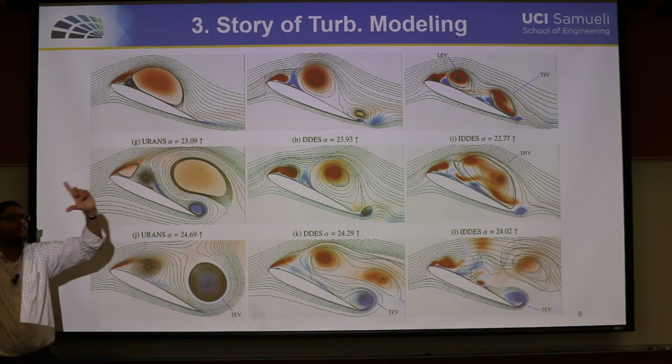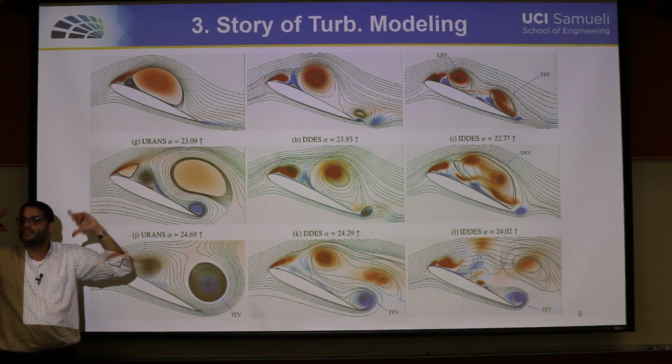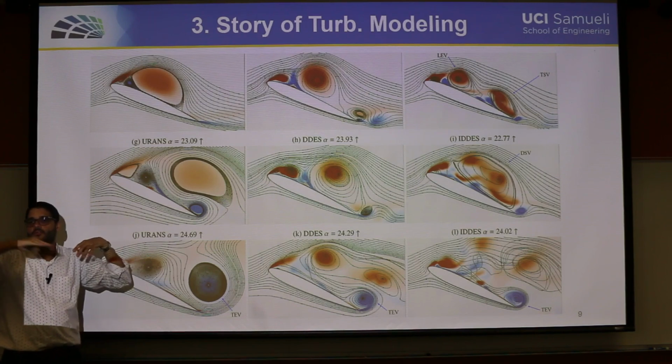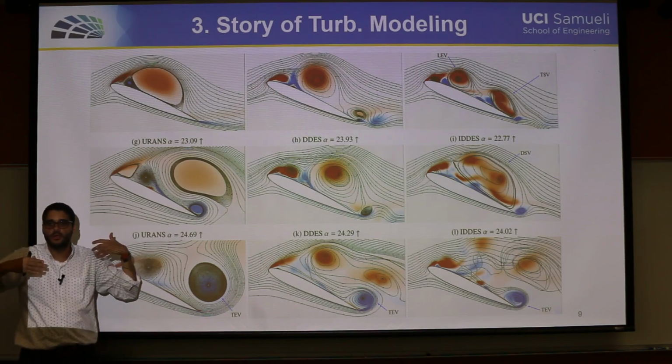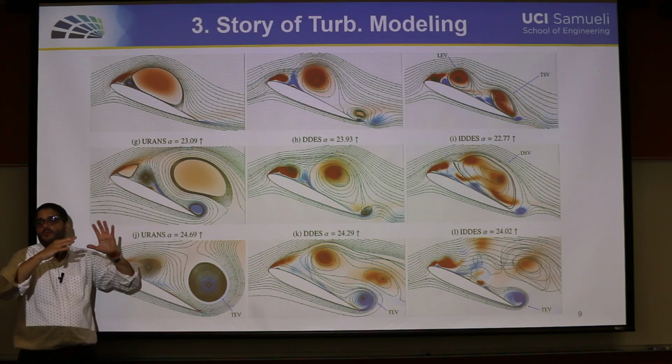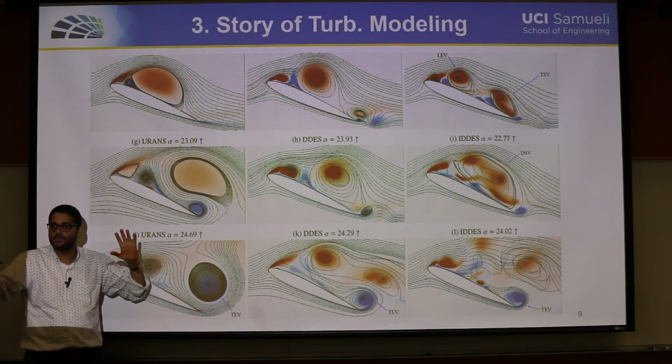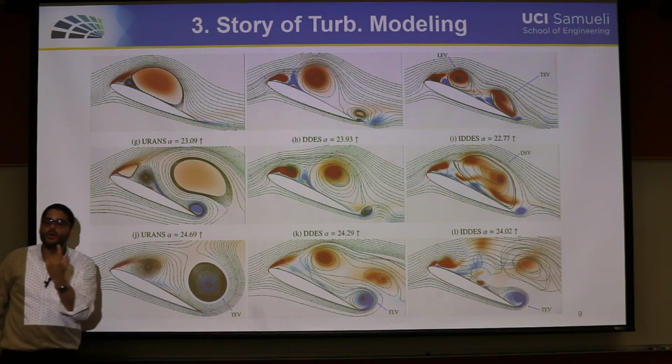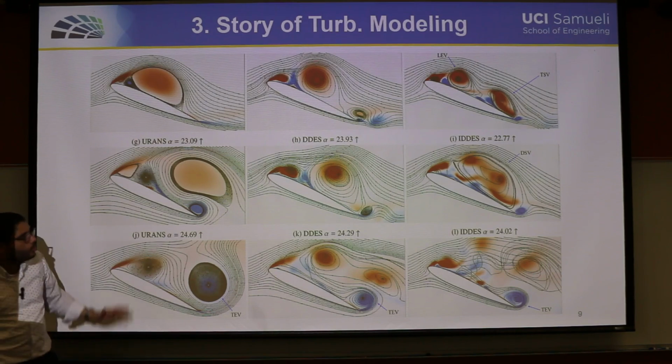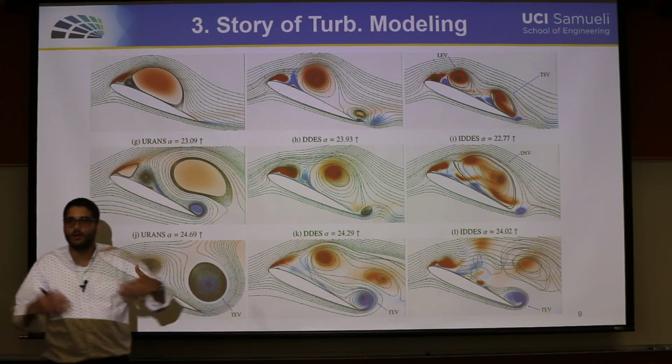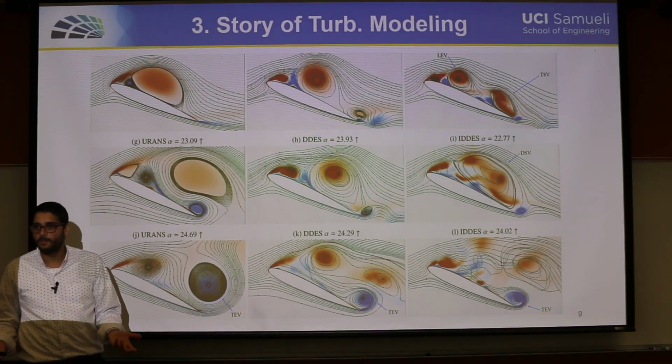If you have just a planar mesh and you extrude it in the Z domain with just 25 or 40 elements, your simulation is now 25 or 40 times larger than one single 2D case. And all of these simulations must be done in an unsteady fashion.